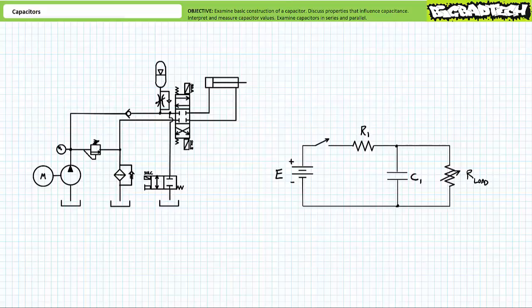Consider this simplified buck chopper circuit, a power electronics device that steps down DC voltage. The moment the switch closes, current rushes into the system, a portion of which charges up the capacitor. The moment the switch opens, the DC source ceases to provide current to the system. However, the charged capacitor can now discharge itself into the load resistor. When this switch is closed and opened repeatedly, the resistive load in effect sees not on again and off again pulses of full current, but rather a relatively constant steady-state value.